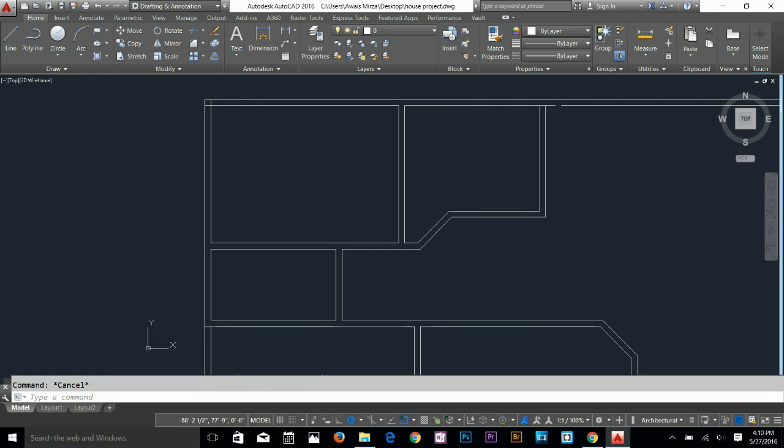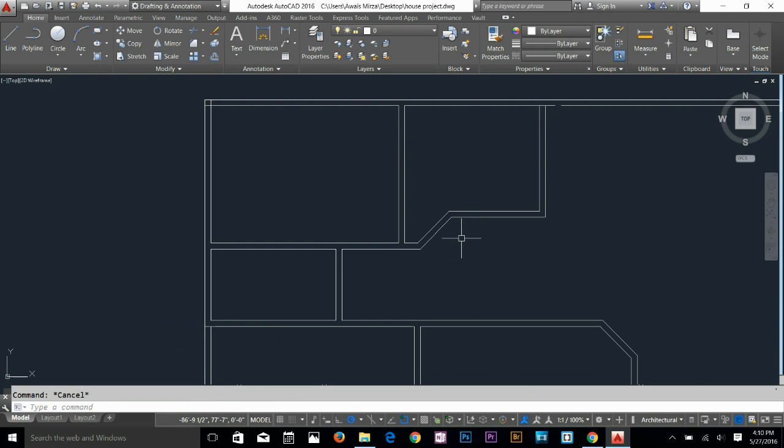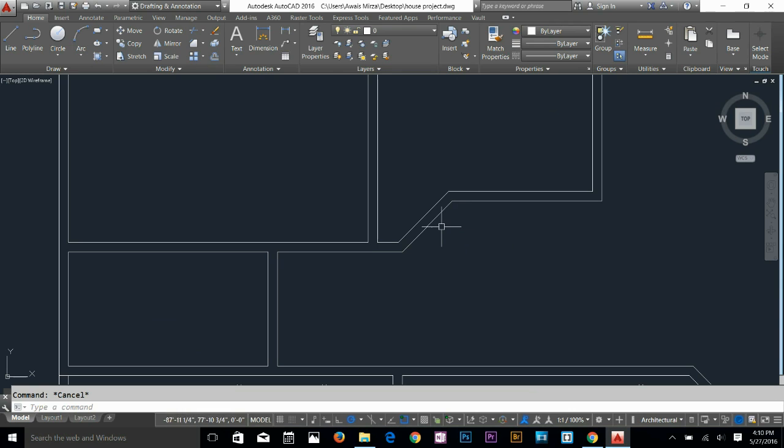Okay, so that's done. Why can't I do it this way? I don't want to use my chamfer command. Actually, I could make a bath here. So I'll just draw a line here, and then use my fillet command, and I've got to draw another line. I've got to offset this 4.5 inch left, and then use your fillet command. Select that, and then select the fillet command again.